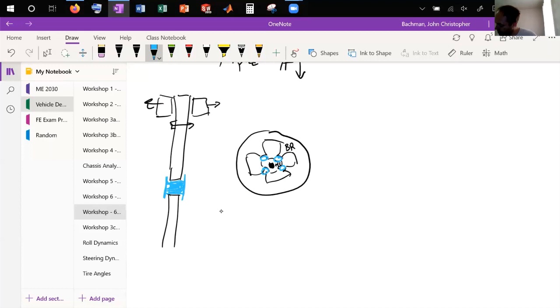And so what this basically does, you can see how it traps it so they're all together. It can't come apart, but it gives play to this part, right? And so that allows it to move if you aren't completely aligned. So this is a floating rotor system. You'll see this on motorcycles and stuff, just to reduce friction, reduce wear. You don't need to line things up as well.